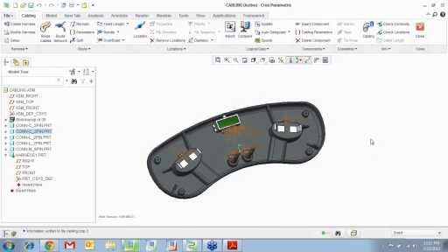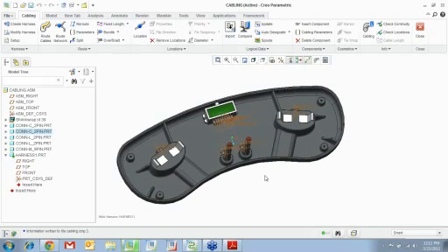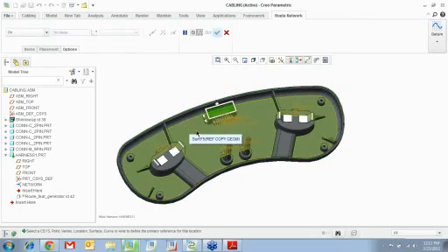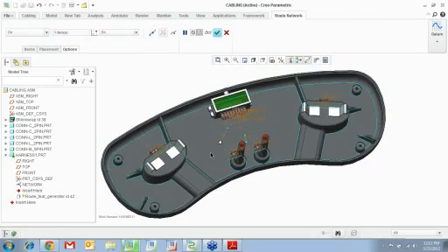Now, once we are at this point, it's about time to create the wire. When you create the wire, you have different routing procedures that you can follow. One of the routing procedures is using a network, right? So I'm going to create a network. A network is like a path that your wire can follow, all right? So I'm going to use a network for a couple of cables, then I'm going to route others without using the network. So I say route a network, and I go 1, 2, 3. I just keep clicking.